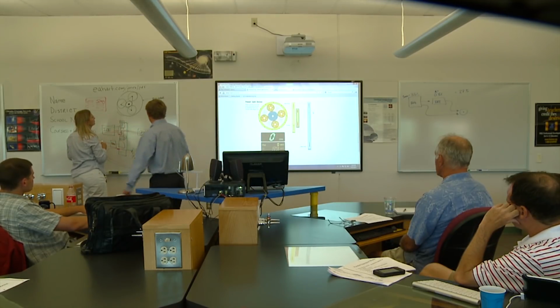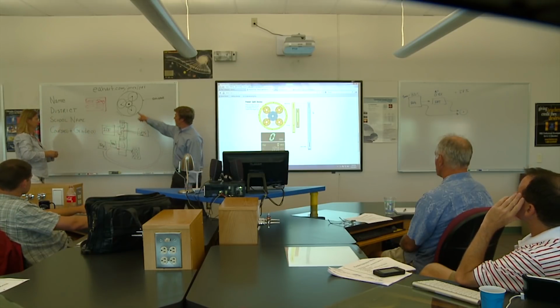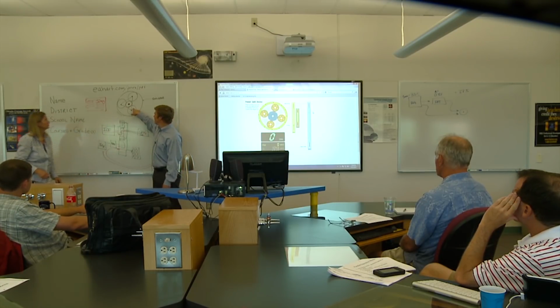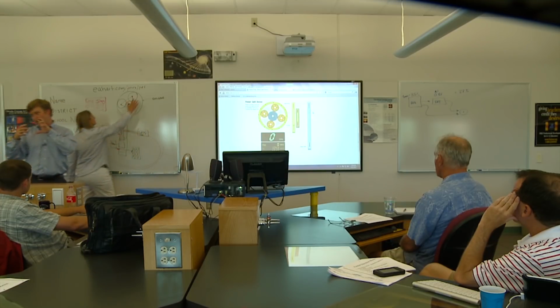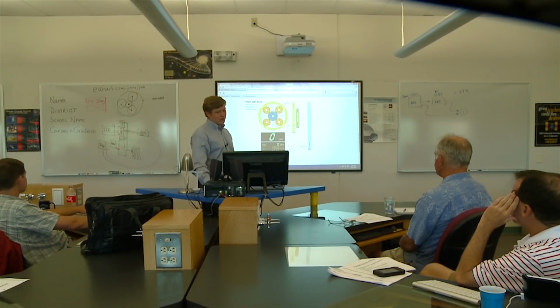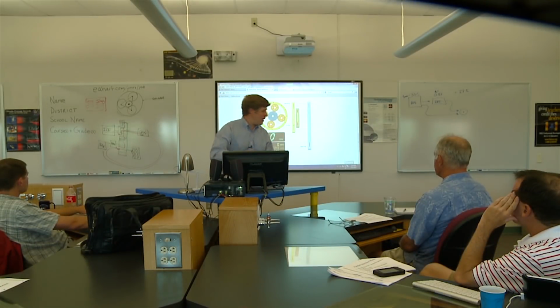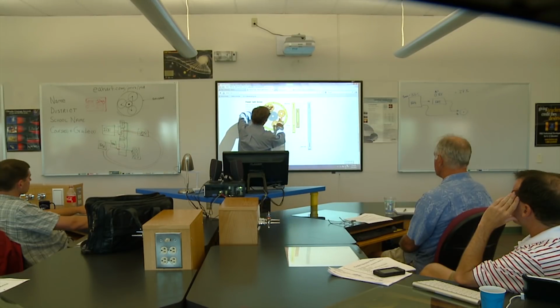So at idle, what's happening is that this generator is spinning, and the sun is spinning, and the planet carrier that's at the ICE is going 1,000 RPM, and their speeds are matched just perfectly, so that actually the output of the wheels of the car are not doing anything. It's really pretty interesting, right? So it takes active control, and this generator actually provides that control. Imagine this planet carrier here is spinning around at exactly this speed. The generator is spinning like crazy, and the wheels are not spinning at all.